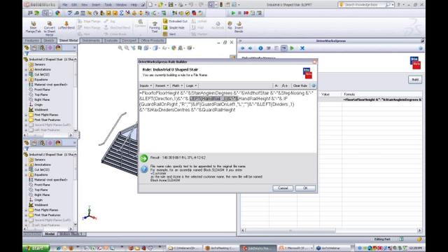What this is saying here is take the handrail selected, if it's left or right, and extract the first character from the left. So you get an L or an R, as you can see down below in the result here, and that's why you get the R's and the L's in there as well as the numbers.